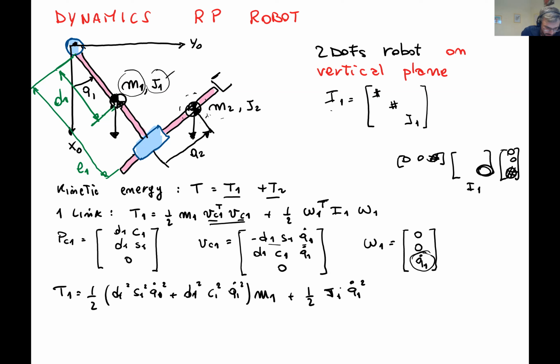It is a quadratic form. If you pay attention, these two terms are summing up to 1, and in essence we have for free what the application of the parallel axis theorem would have given us if we want to compute the inertia not with respect to the center of mass, but with respect to the rotating axis, which is here.